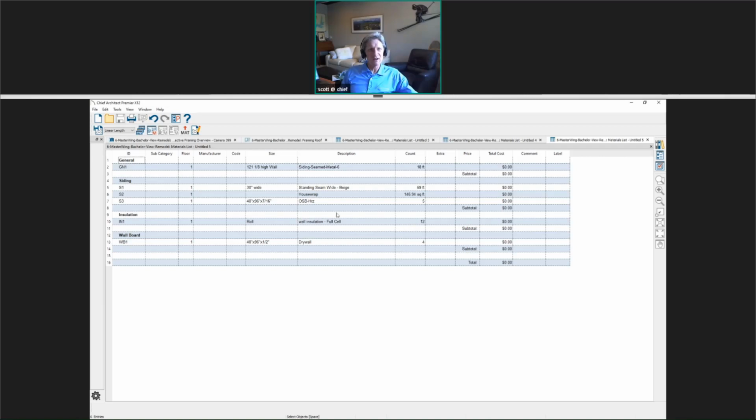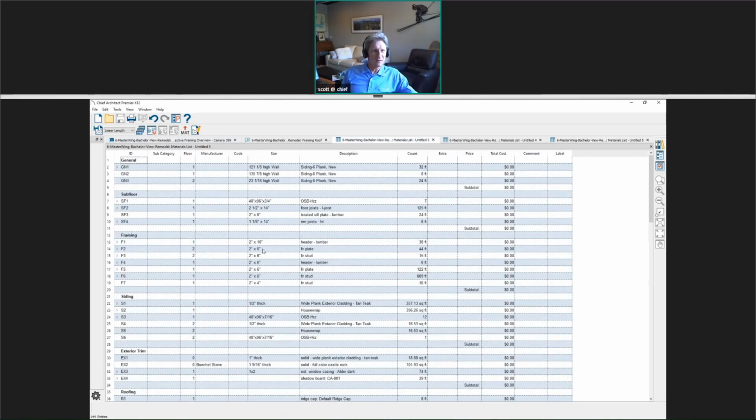you would have to put the formula in there, because if you look at the overall materials list and we look at that wall, you're getting how many lineal feet of a particular wall. So I'd probably need to do a test case and make sure, if you had a 10-foot wall, 10-foot length, 10-foot high, so you have 100 square feet, you just want to check that calculation, verify that you have the right formula. I think you should be able to do it, though.